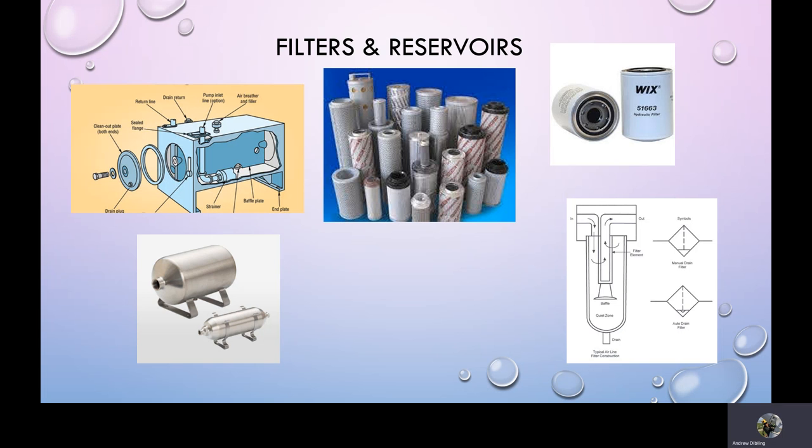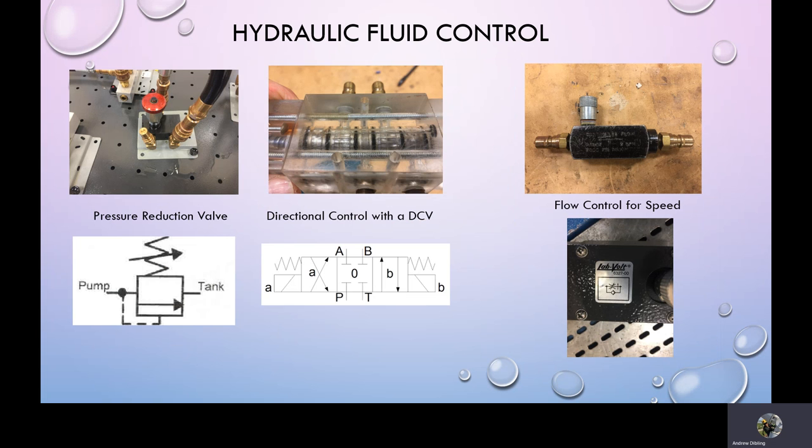to the pump. And there you see on the top right-hand corner and in the middle there, the different types of filters that are available. Some of them are screw-on, very much like the oil filter on a car, and some of them are cartridge filters that go inside a sleeve and a cap, depending on where they are in the system and the system's design. A smaller system will have the screw-on type that you see in the top right-hand corner, where larger systems will have filter elements, which are a little bit more expensive and more specialty.